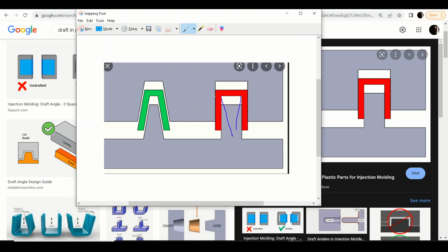You cannot pull out the part, because it was manufactured in this way, and after cooling down from higher temperatures, it will be solidified in this shape. You cannot pull the material outside because it is jammed over here. That is the reason you have gaps over here that will help you pull the part easily outward.